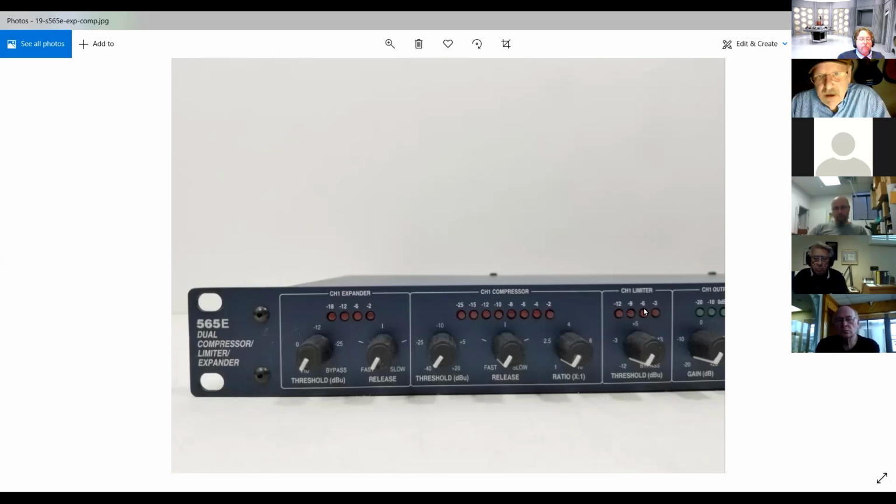This is a very important point that I made in the original SBE processing course that we put online. Your compressor has to do a good job at holding the level constant, as natural a sound as possible. But he's got to hold that level reasonably constant. On the other hand, you don't want too much processing in there. You don't want him reacting to transient peaks because that gives the limiter nothing to do.